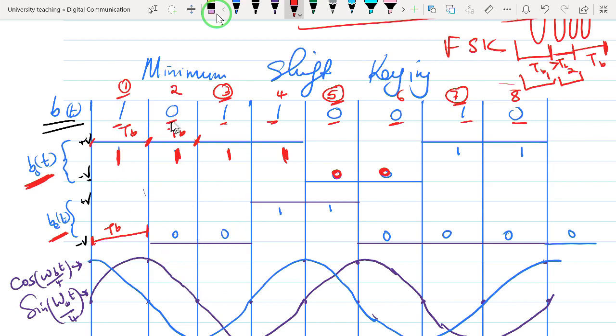So we say that this one starts at 0. Therefore, it's going to have bipolar non-return-to-zero encoding, and that means that 0 is going to have a negative voltage, just like we did with this one. So we have seen that this is a 1 bit duration delay, and therefore our even bits start at TB, the second TB. Therefore, we say that this one will take 2 bit durations.